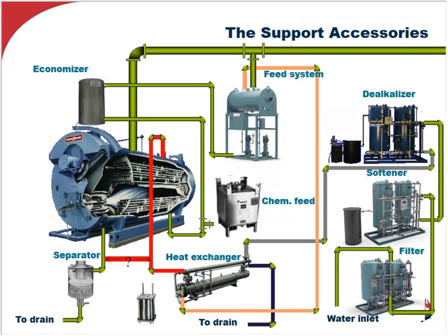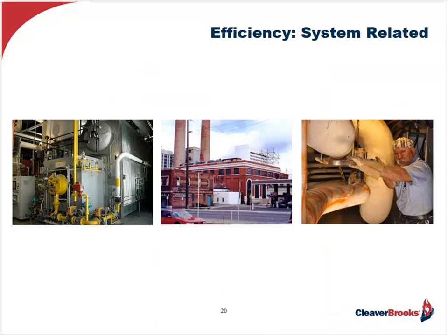And what about the boiler feed? Is it a vented receiver or a deaerator? What's the operating temperature? Can it be elevated? How are the boilers fed? With on-off pumps? Modulating feed with constant running pumps? Well, what about a variable frequency drive on these pumps, the ones that are constant speed? How about the chemical feed system? And where are the chemicals going? Into the feed tank, or are they going into the boiler? These are all very important observations which need to be taken into account, and then they have to be documented in an assessment.